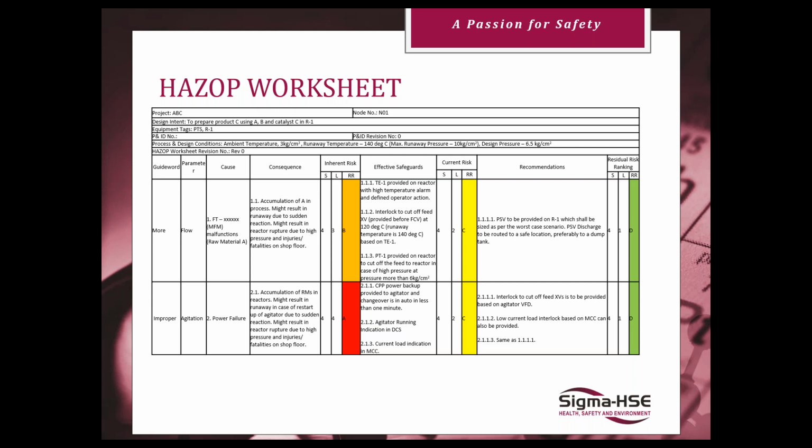Severity of 4, which would be your potential fatality. Likelihood of 3, instrument failure is generally a 1 in 10-year event, which is where the 3 comes from. A risk of B, which as you can see is orange, which in this risk matrix is an unacceptable risk. And then you look at, okay, what safeguards do you have in place already to reduce this risk?